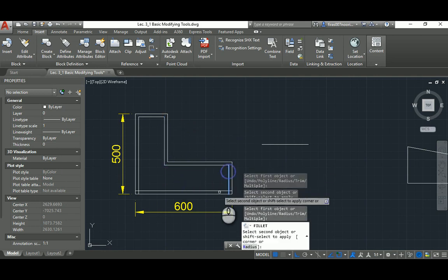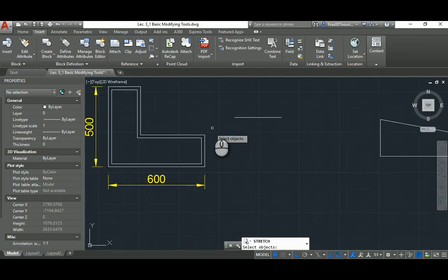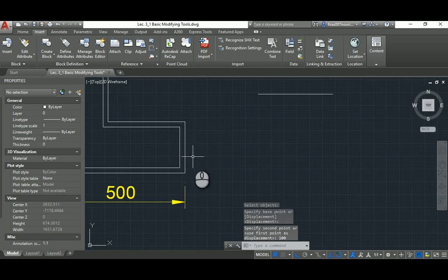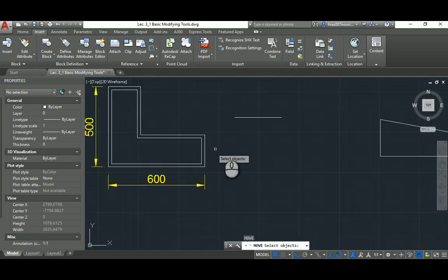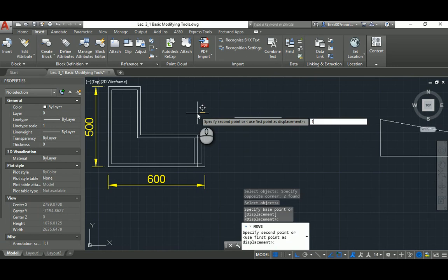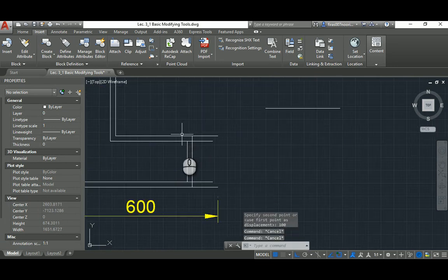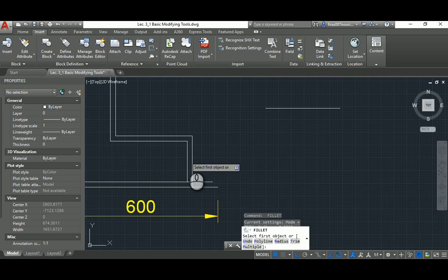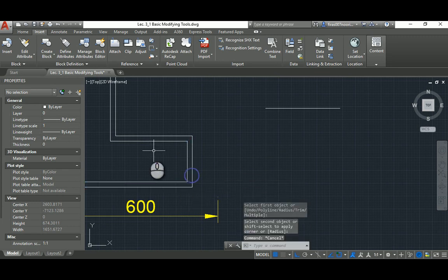So if I did this again, if you remember, and create the walls that I have, now I can stretch this as a plan again together, doing this. See, 100. Beautiful. Otherwise you will be in the trouble of using move, push that 100, and then fillet again. Kind of a boring business if you don't know how to use the stretch command properly.